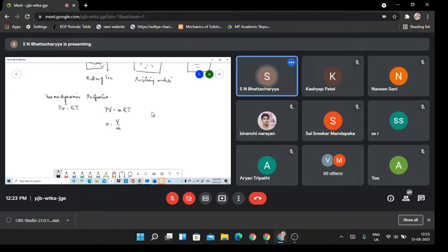Now, the triple point is rarely of concern to engineers. If you are dealing with a boiler, we are dealing with water and vapor in equilibrium. So there, if it is saturated, I require one coordinate. It could be either pressure or temperature. So the properties of saturated water, where the liquid is in equilibrium with vapor, are tabulated either using temperature or using pressure. So two tables exist.